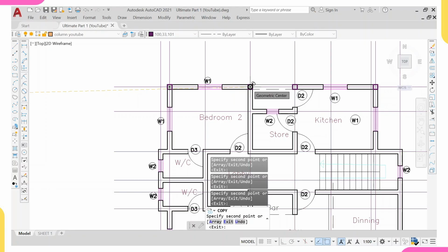And what it implies is that the more the span, the more the moment, and the more the reinforcement that you will be having. For example, if you go beyond 6 meters, you might be having, let me say, 5Y16 or even 3Y20 or even 2Y25. Because we don't really want all this larger reinforcement or too many reinforcement bars, that's why we advise that you should limit your column spacing to below 6 meters.